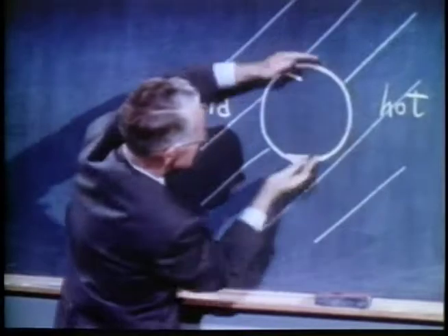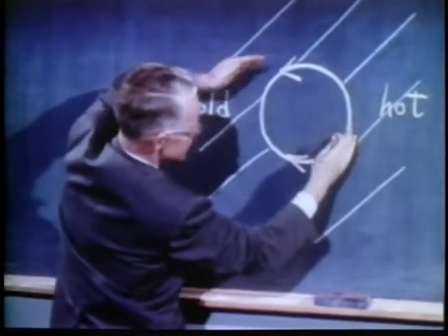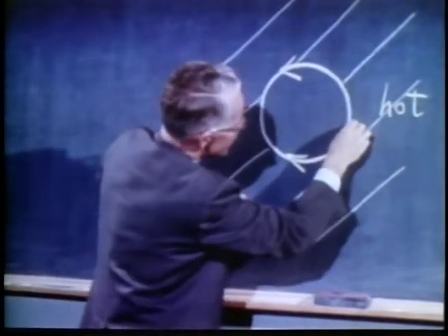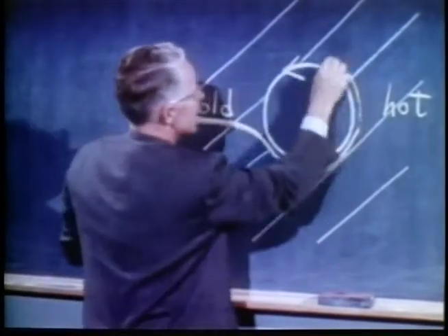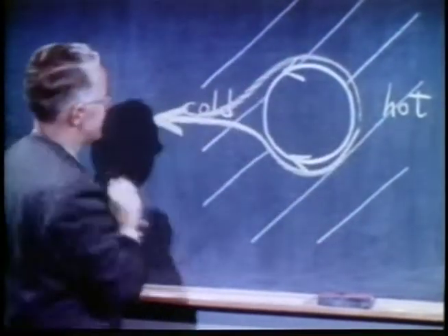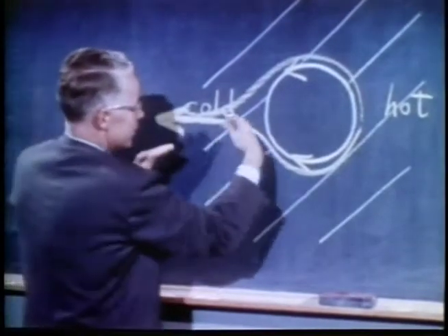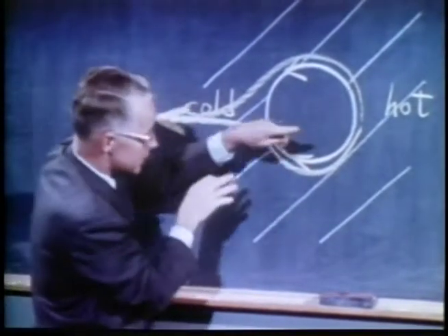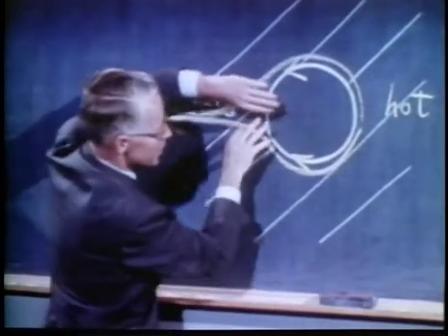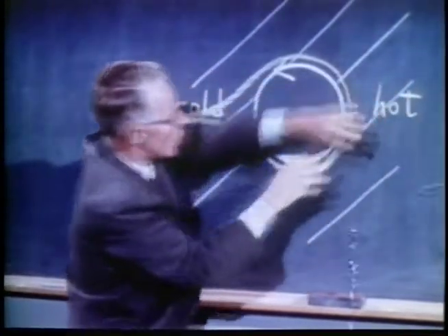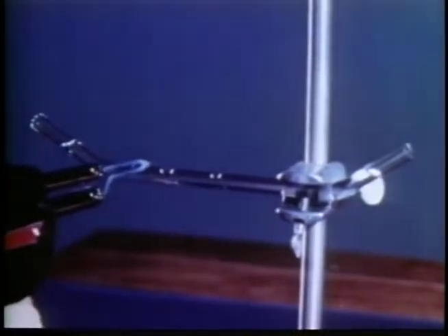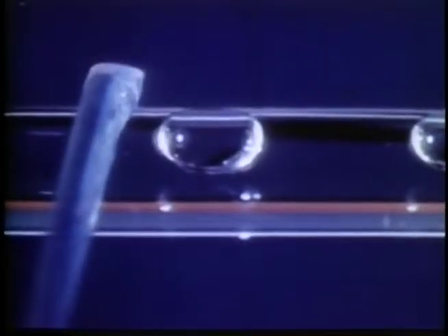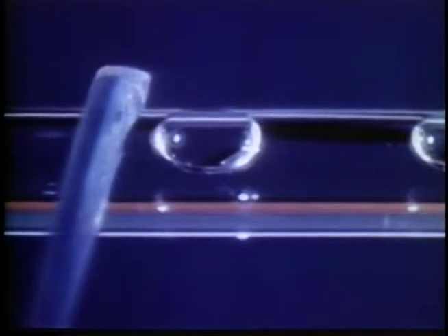This movement of surface with this viscous drag upon the boundary fluid will pick up a sheath of liquid and jet it off the back end. By jetting liquid this way, the bubble propels itself that way. It will swim up the temperature gradient, always moving to the hot region. Here we have a bubble. It moves to any hot region.